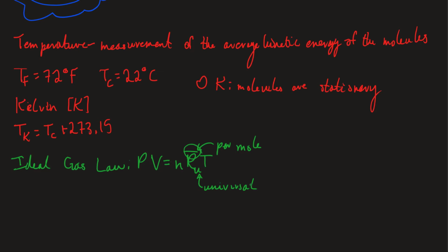Now, a slightly different form of the same ideal gas law is a little more useful in most of our thermodynamics problems. So we'll go to this slightly more useful form by taking the number of moles and expressing it in its definition. So the number of moles is equal to the mass over the molar mass. And so we keep the other terms the same. And if we move this molar mass division to the universal gas constant, we get this mass times this gas-specific constant